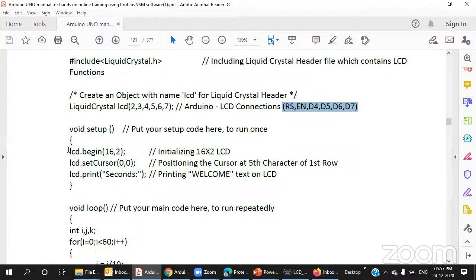Here first we are taking the begin function, lcd.begin. lcd.begin represents LCD functions. This is the initialization. If we were writing it ourselves, we would create our own name like LCD initialization. Here begin is initialization. We will set this function every time in setup only.